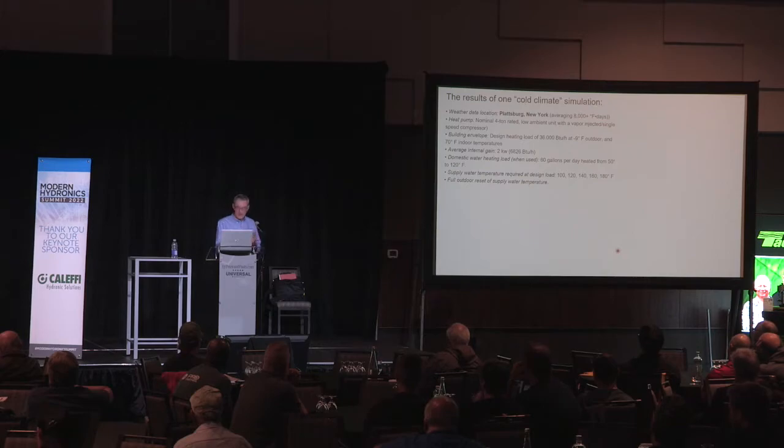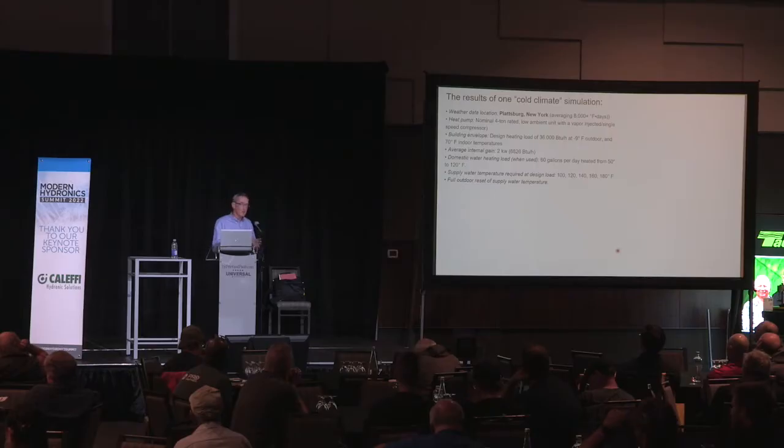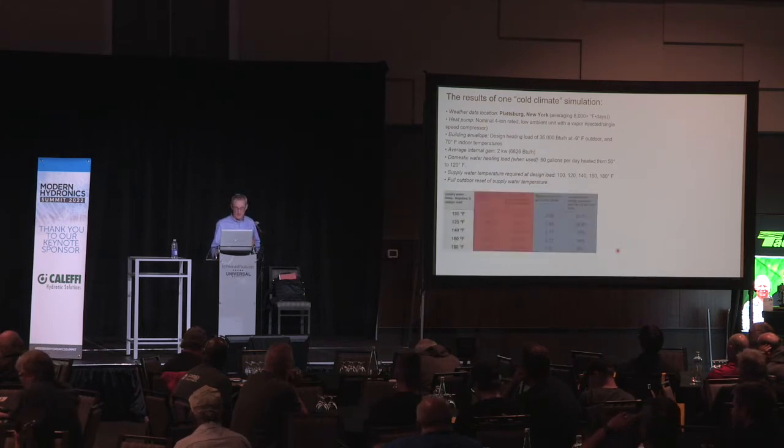The other thing, and I guess I didn't put it on here, we did not allow the heat pump to supply any load that required more than 130 degree Fahrenheit water temperature. Many of the air-to-water units that are out there now can do 130. Some can actually do higher. Now, again, performance does go down in terms of COP, but they are capable of sustaining 130 degrees, even at, say, 0 degrees outside. In our simulations, we did not allow any heat pump energy input when we were requiring a water temperature above 130.